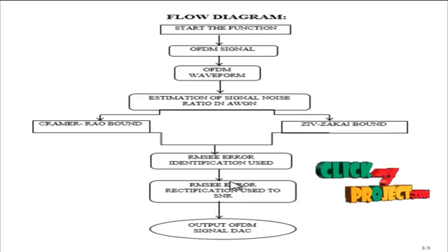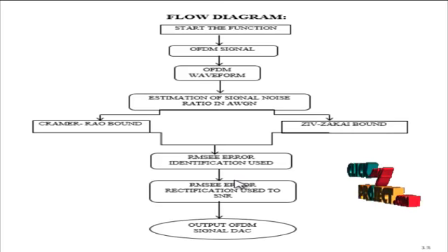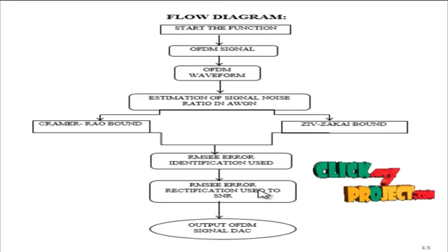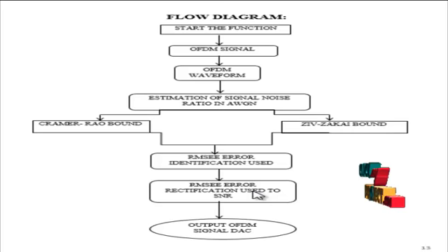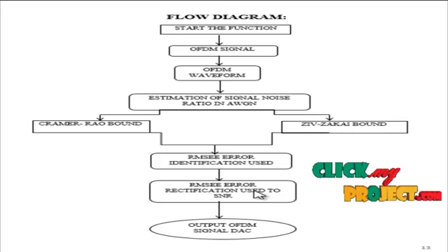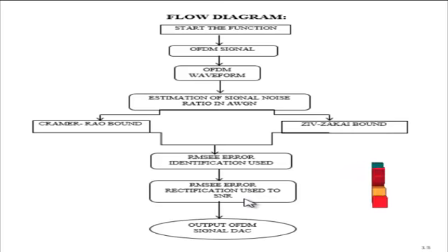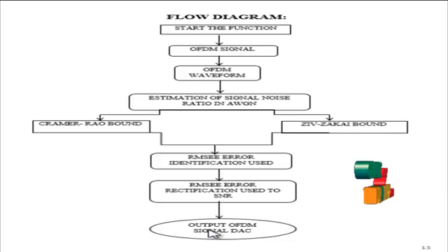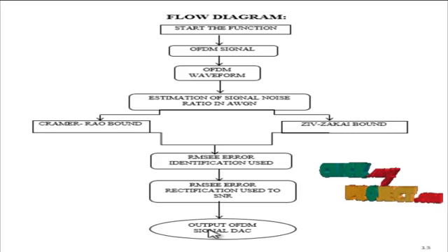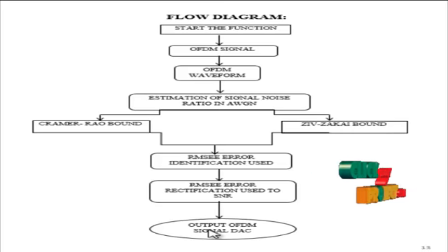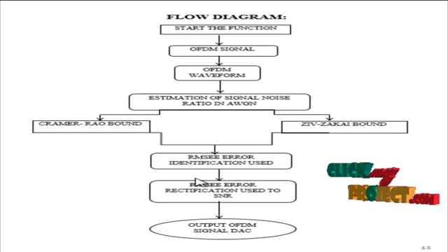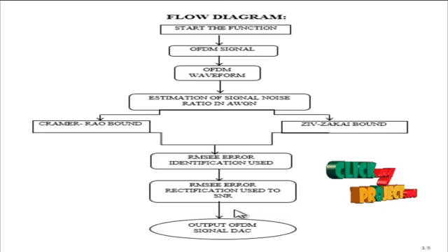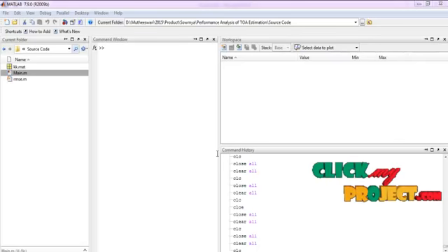A direct comparison shows a satisfactory agreement between the two definitions of the SNR threshold, further revealing that the ZZB in the boundary between TR and AR is sufficiently steep, and the performance analysis of SNR and RMSE are performed. Two sets of power distribution of the available subcarriers have been defined to evaluate the RMSE performance both in the asymptotic and threshold region by using CRB and ZZB. The developed analysis has confirmed that for a given maximum bandwidth, the power distribution influences RMSE both in asymptotic and threshold region. Let me discuss the running procedure for our process.